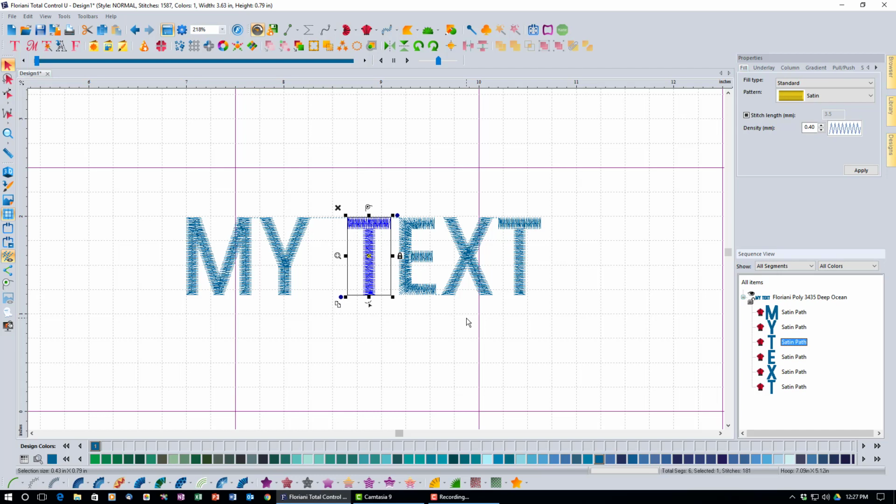If you just did it by mistake, you could undo it, but the minute you start manipulating this, you're not going to be able to go back to text unless you undo all the way back. So the take home from this is if you want to break up this text, make sure you have all the characters exactly the way you want them before you do that. So that's one of the advanced controls that you can do with breaking up the text.